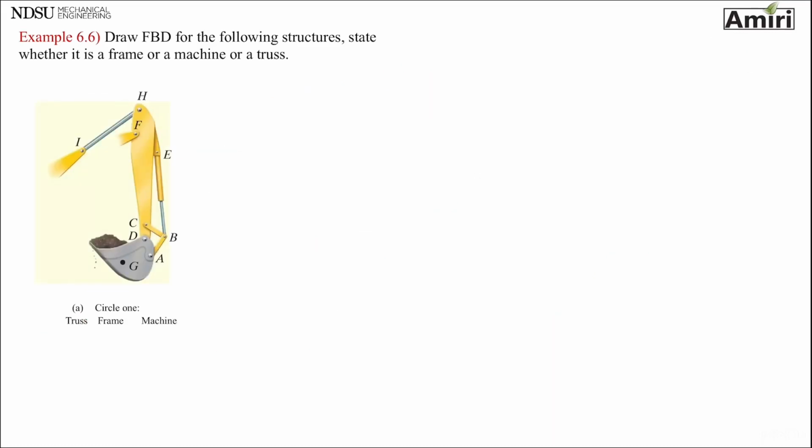Let's look at this one. Well, it's not a truss for sure. It's a movable part for transferring load, so it's a machine. As soon as I know it's a machine, meaning I have to draw or disassemble its members. How much you want to disassemble it is totally up to you. Okay, I'm going to have this member, this huge main arm, and then I'm going to take another member. I'm assuming that this is connected somewhere back there, so IH,